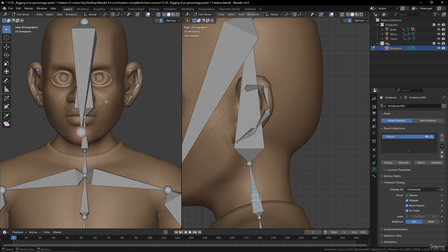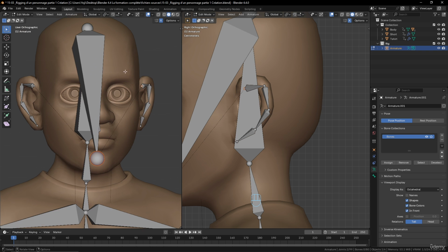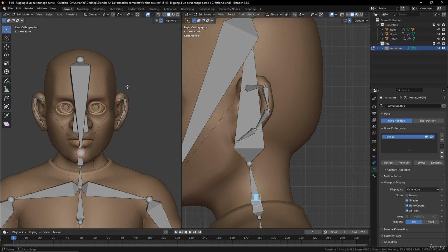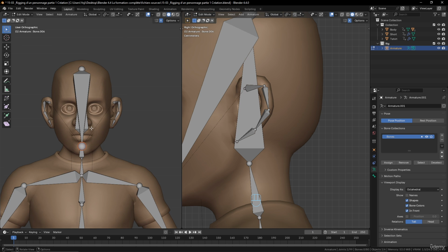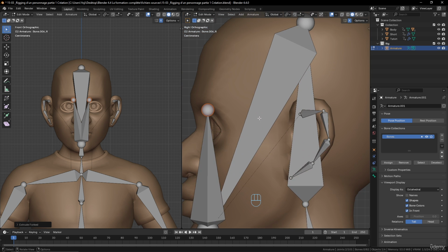We can remove that one again. It will keep the relationship between the two. I will make this same kind of thing over there. So I make an extrusion again in front view. Put it here. Sorry, not an extrusion. A double extrusion with Shift E. Okay, come there.